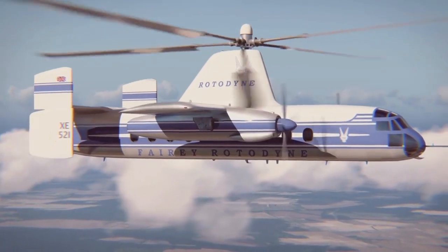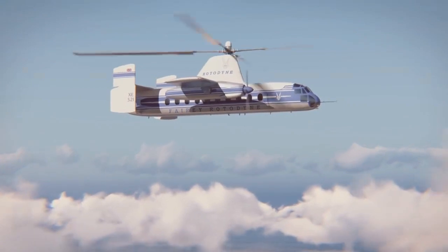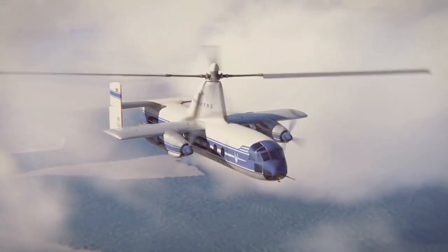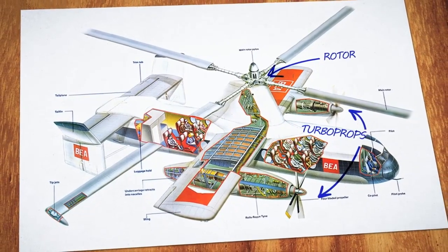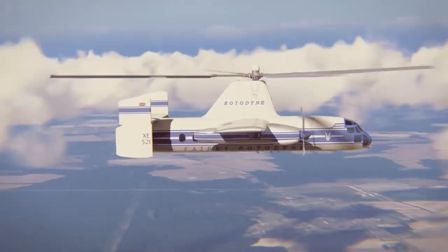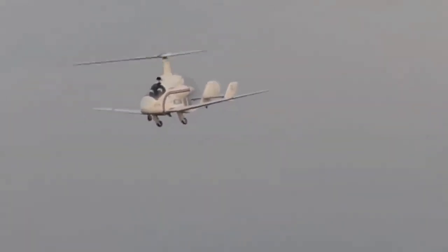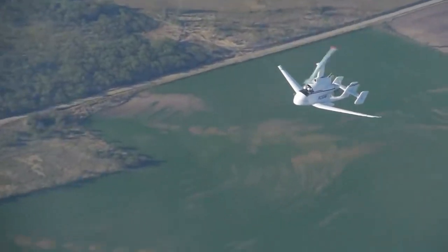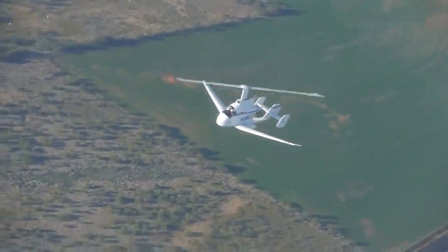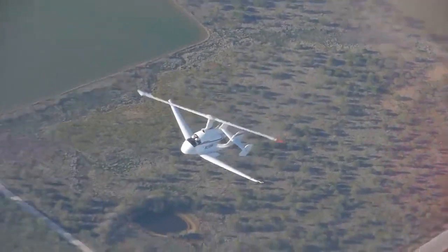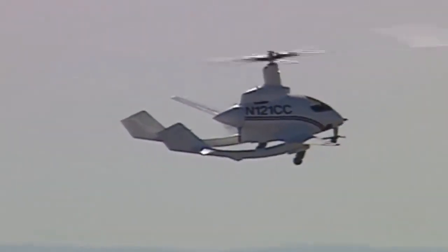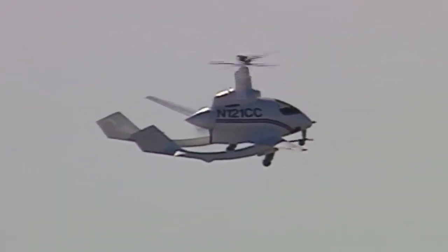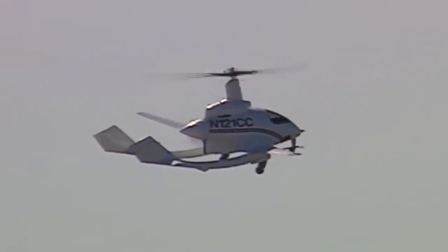A gyrodyne is a rotorcraft with a rotor system that is normally driven by its engine for takeoff and landing, hovering like a helicopter, and its forward thrust is obtained from a separate propulsion device rather than from tilting the rotor. An autogyro, sometimes called gyrocopter, gyroplane, or rotoplane, utilizes an unpowered rotor driven by aerodynamic forces in a state of autorotation to develop lift, and an engine-powered propeller, similar to that of a fixed-wing aircraft, to provide thrust.